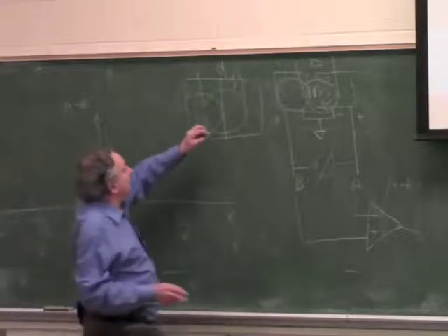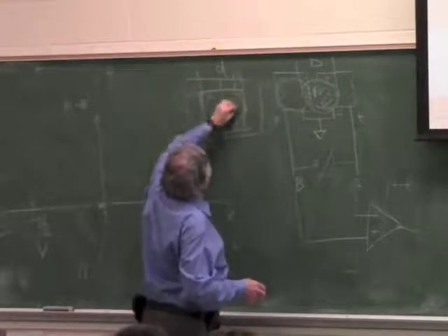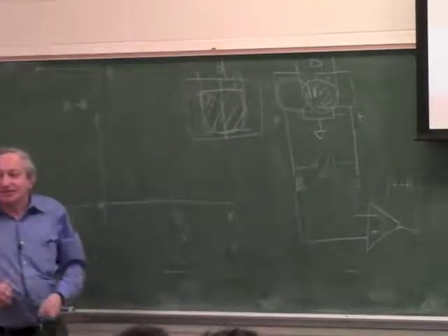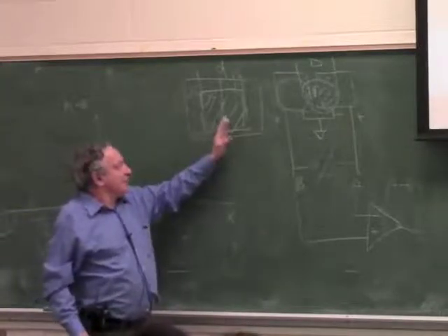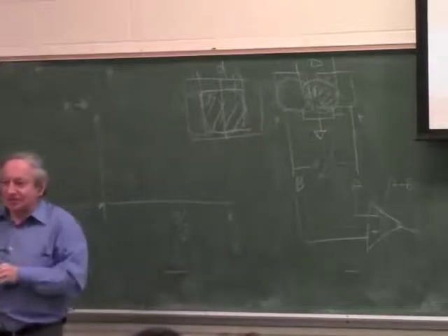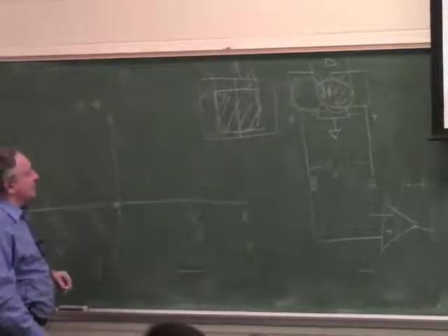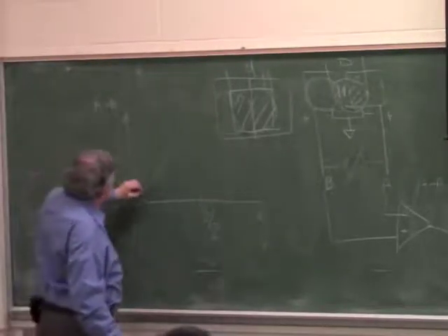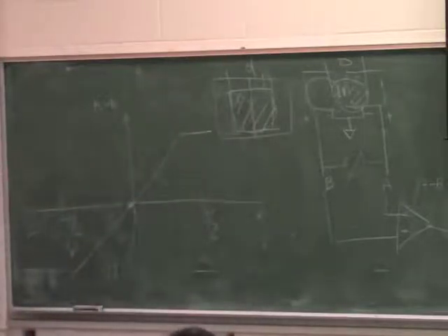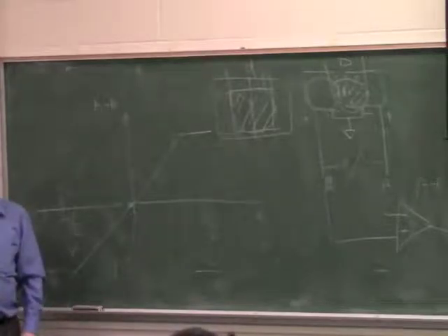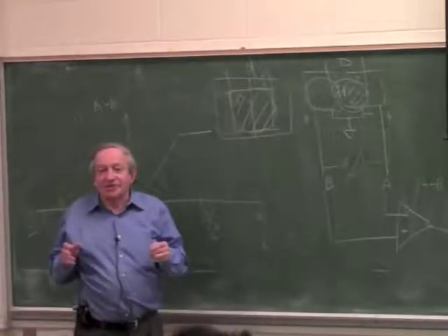For example, if this was a rectangle of light, if I replace this with a square of light, then it will be completely linear, assuming the square is uniformly lit. Because as I move that square of light, more and more area is covered by the same intensity of light. So let's say, just for argument's sake, I have the light in shape of a square. So this will look like this, and when it comes to D over 2, it will saturate. So it will be a very nice linear range. It will be differential. And I can scale this up any size I want.